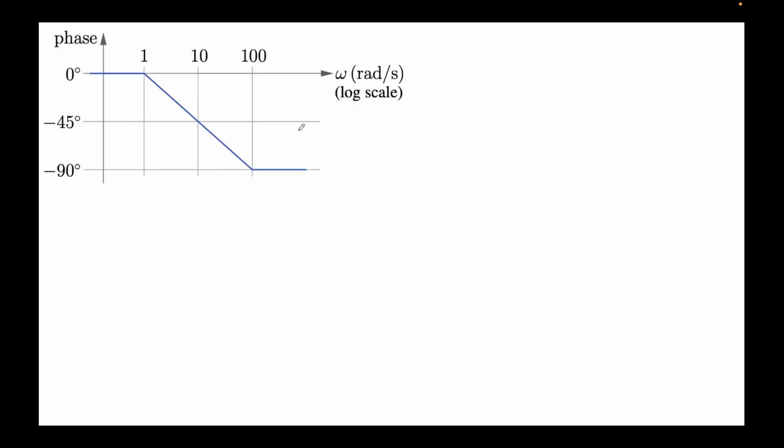Okay, so the key thing to note here is, first of all, what is the 3 dB frequency. First thing, note the 3 dB frequency. We notice this is the 3 dB frequency. In the magnitude plot, where there is a kink, where the slope changes, that's the 3 dB frequency. In phase plots, it is in the middle of the two slopes. Okay, so between 1 and 100, it must be in the central part, right? Omega equal to 10. So we see that it is omega equal to 10. At omega equal to 10, units are radians per second, right?